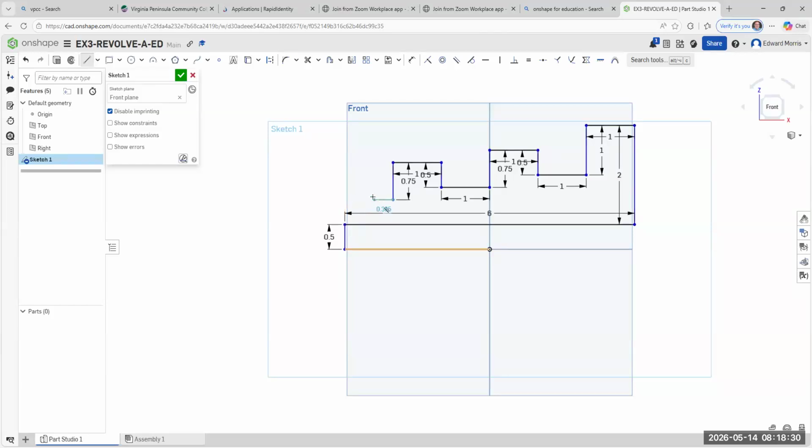Okay, now watch what happens when I move to the left. You will see it stop for a brief second. That's because that point is now lined up with your initial point. So we are going to stop right there. Click and we're going to enter. You may not have to enter because it already knows that it's even with that point. And come here and close the profile. Click. All right. Now, enter.